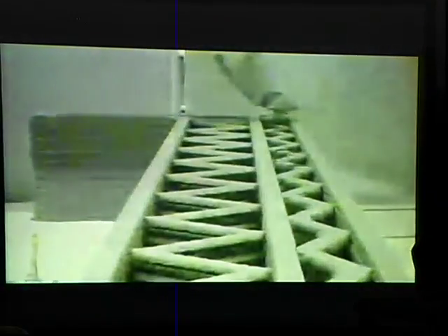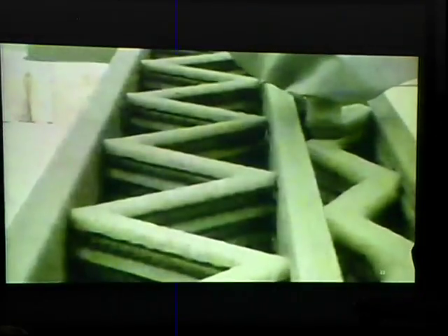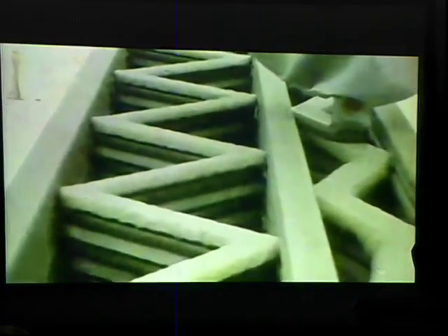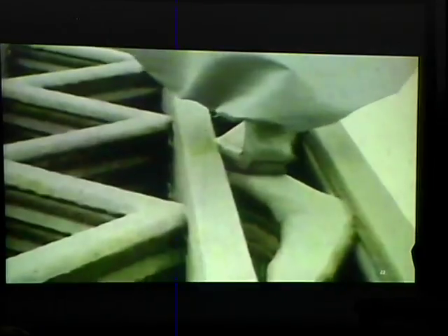So the other way to do this: everything that we talked about in CNC machining is what we call subtractive manufacturing. You can also use this for additive manufacturing. You could, for example, 3D print a house. This is a concrete 3D printer. What you can see here starts to immediately look familiar as we learn about G code, right? That's a G01 command. That's moving in a straight line. That's moving in a straight line. It's just straight line after straight line after straight line. And it keeps going until you've actually built something up.